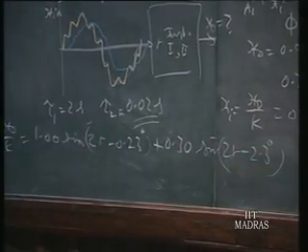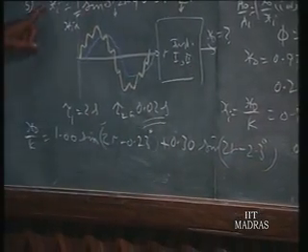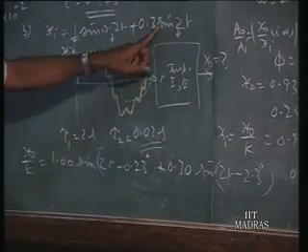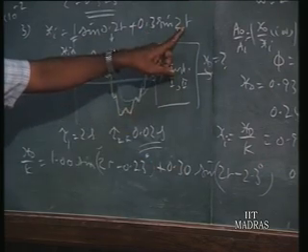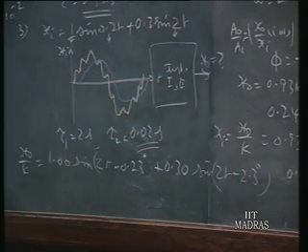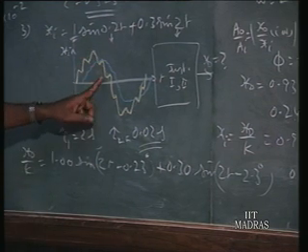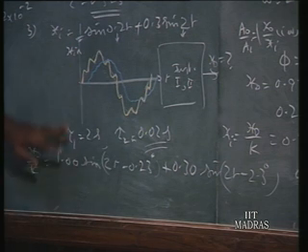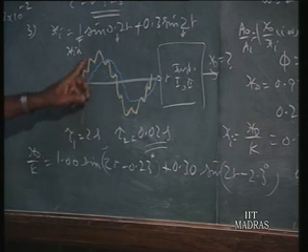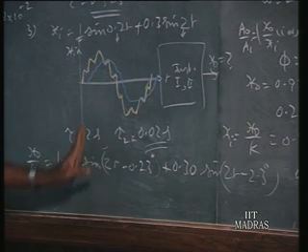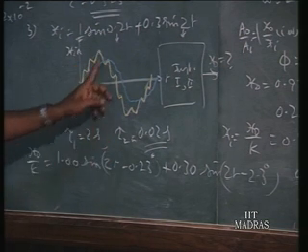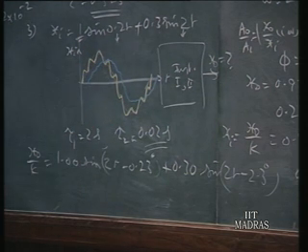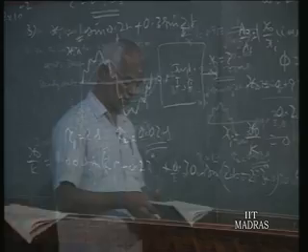So now you find the original signal is almost there up to second decimal. Here is a very small phase lag, and here also the amplitude remains the same, and the time lag, the phase lag, is also very small. So for such a signal where there is a high frequency component, we should always go for an instrument having very low time constant. Then only the input signal will be truthfully reproduced on the output side. Otherwise, the higher time constant instruments will eat away the high frequency component. So that is well demonstrated by this example.